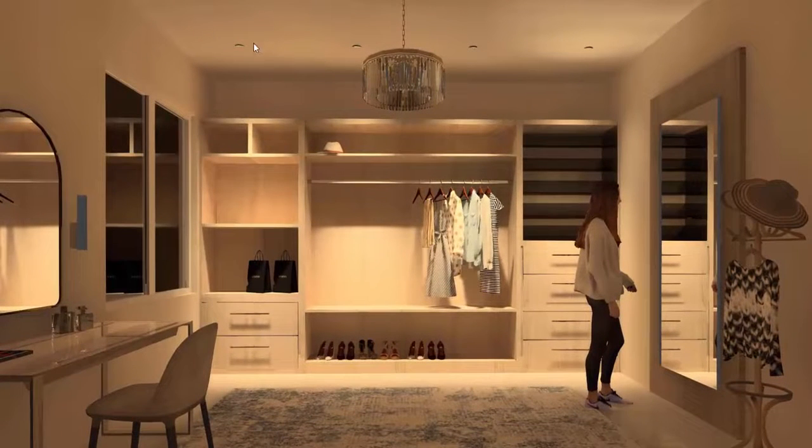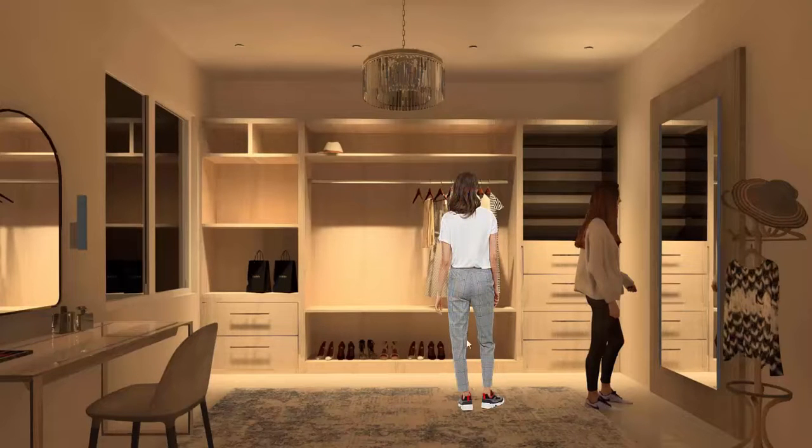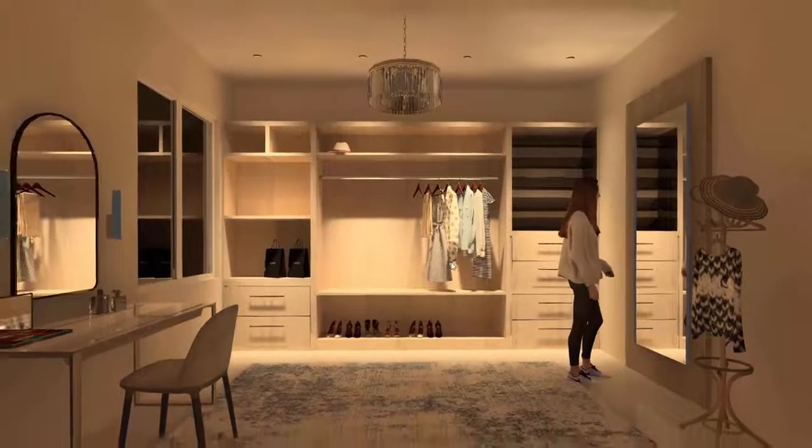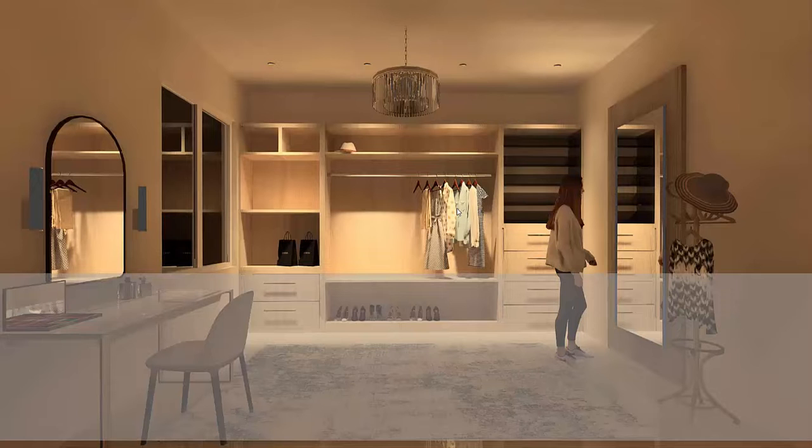This is also the place, the use of this adjustable downlights is also crucial, because if some person is standing right in front of this closet in this position here and picking up the clothes, I have a downlight here, it may fall on the person and there might be a shadow of the person falling here. Okay, so the proper positioning of this downlight is important in case you're not using any additional joinery lighting for your closet. I would suggest you to use adjustable downlight instead of fixed downlight.